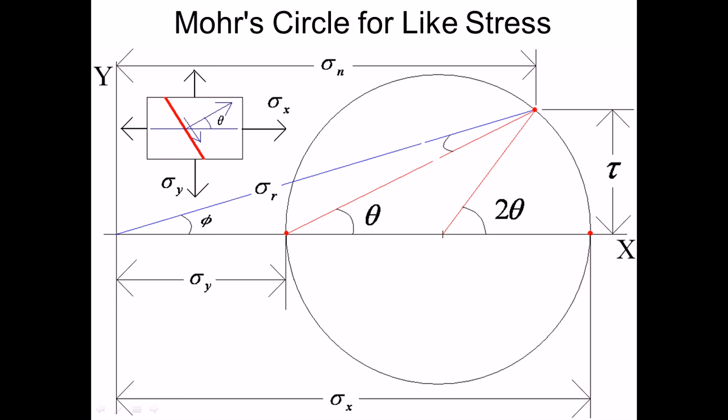To draw a Mohr circle, first we have to draw the question figure. In the question figure, sigma x and sigma y are acting, and there is no shear stress in the vertical and horizontal planes, there is an inclined plane, and on the inclined plane sigma n and tau are acting. The sigma n is at angle theta degree to the direction of application of sigma x. So this is your vertical plane and this is your horizontal plane.